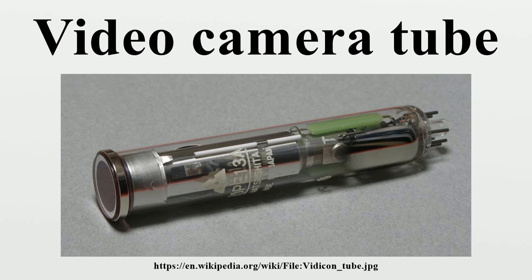The image Iconoscope is essentially identical to the Super Emitron, but the target is constructed of a thin layer of isolating material placed on top of a conductive base. The mosaic of metallic granules is missing. Therefore, secondary electrons are emitted from the surface of the isolating material when the electron image reaches the target, and the resulting positive charges are stored directly onto the surface of the isolating material.